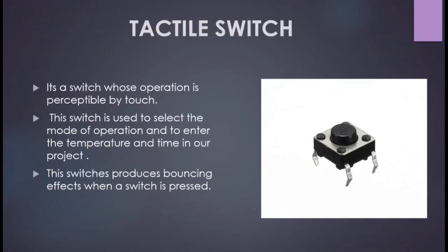Next one is the tactile switch. A tactile switch is one type of widely used switch that completes an electrical circuit, typically when pressure is applied to the device by the user, which then gives the user a perceptible click in response, indicating the current flow. Current flow is turned off when the switch is released.